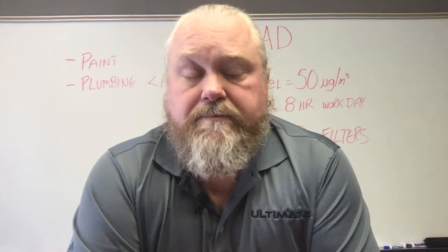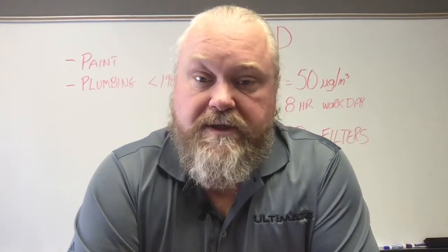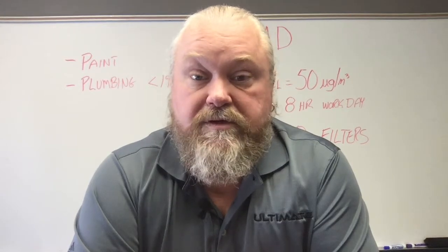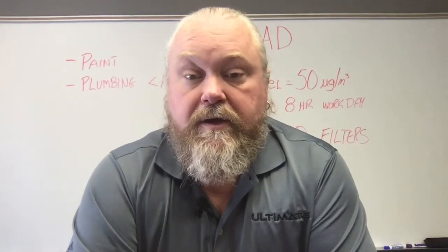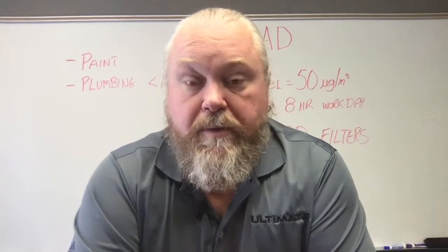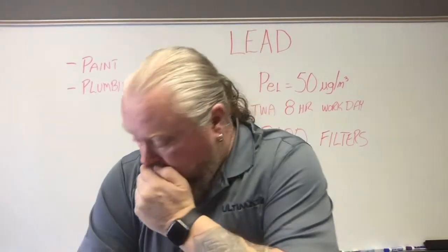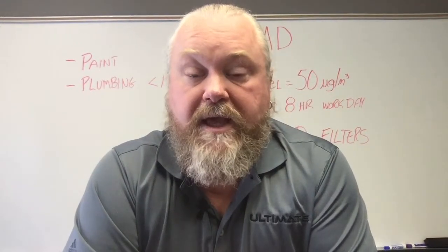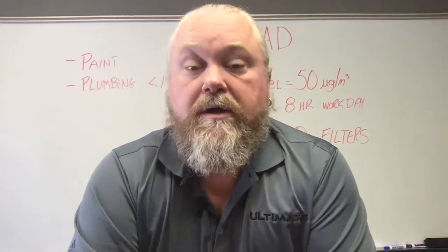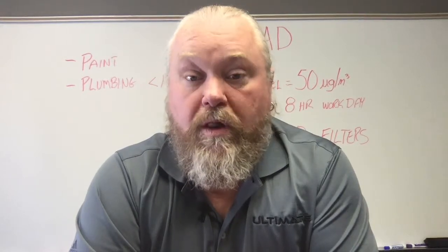Well, how do I know if it's lead? Well, you're going to have it tested in order to find that out. So if you are messing with some systems that have been there for several years, especially in the commercial environment, you're removing that paint, especially off of steel, is primarily where you're going to find it to prevent that rusting to happen. So once we identify that paint as lead based, then we make sure that we don't utilize any kind of practices or procedures with that material until we're certified to do so and we're qualified in order to be in that environment.